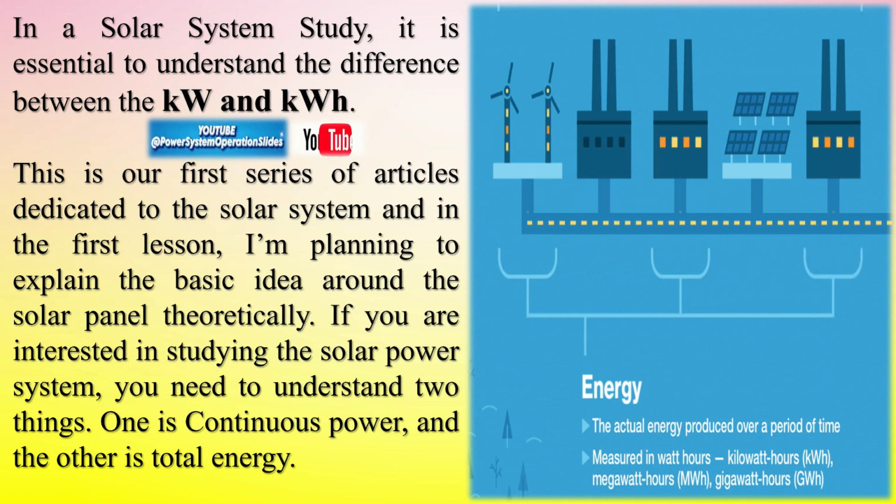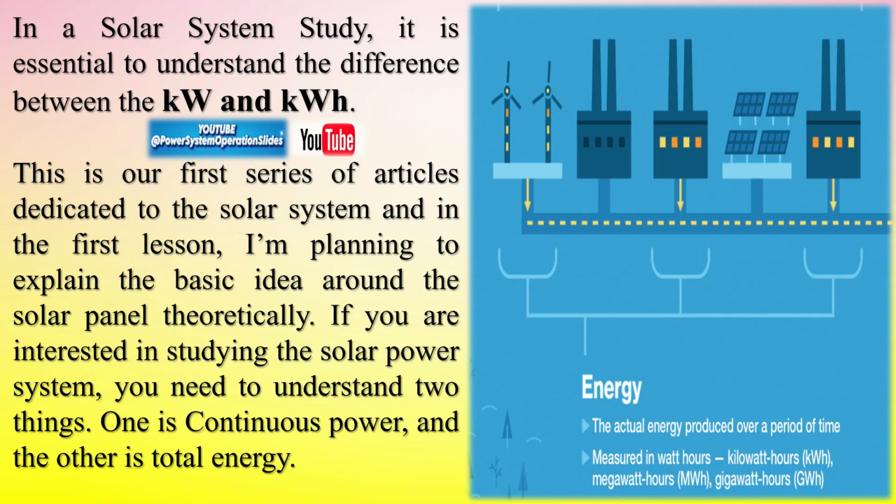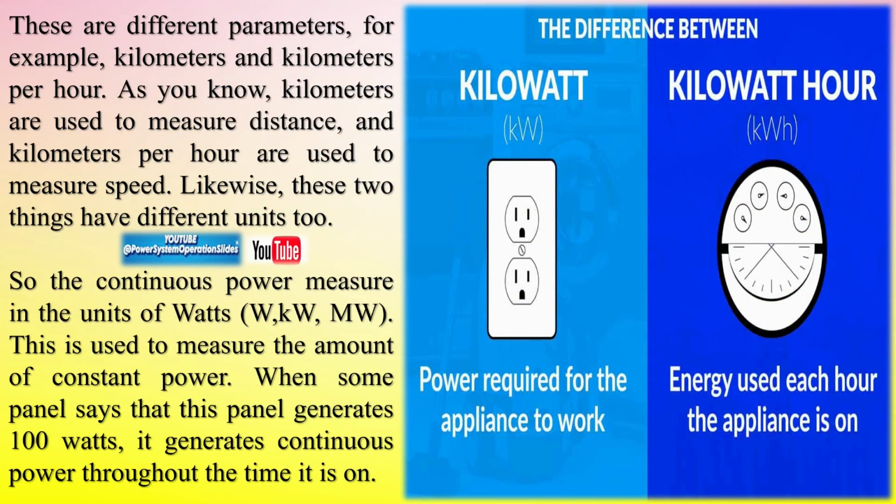In industries or households, power meters measure the kW being used in real time. These devices give an instant snapshot of how much power appliances or machinery are drawing at that moment. Real-time kW measurements are important for identifying high power demand, monitoring system load for peak demand management, and ensuring that electrical circuits are not overloaded. Energy meters for kilowatt-hour measurement.